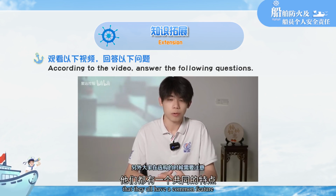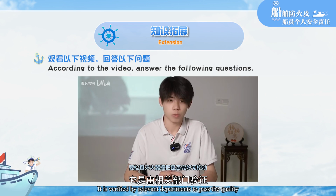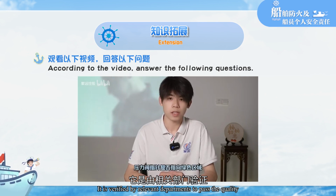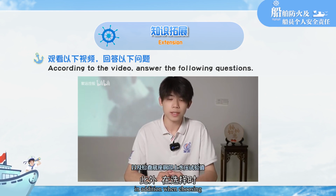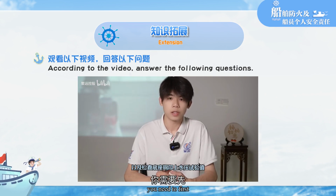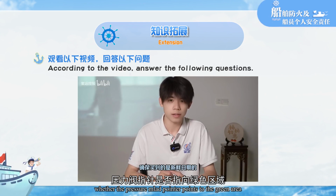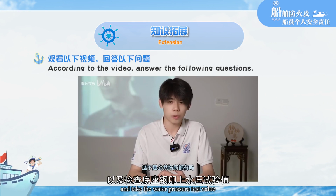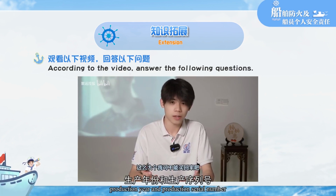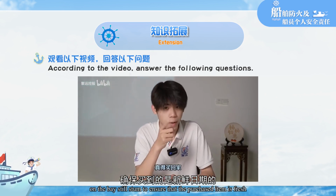After watching the video for so long, I don't know if you have noticed that they all have a common feature, which is a red S mark. This mark is not simple, as it has been verified by relevant departments to pass the quality certification. Without this mark, we dare not use it. In addition, when choosing, you need to first check whether the fire extinguisher handle is intact and not loose, whether the pressure valve pointer points to the green area, whether the lead seal is complete, and check the water pressure test value, production year, and production serial number on the base steel stamp to ensure that the purchased item is fresh.